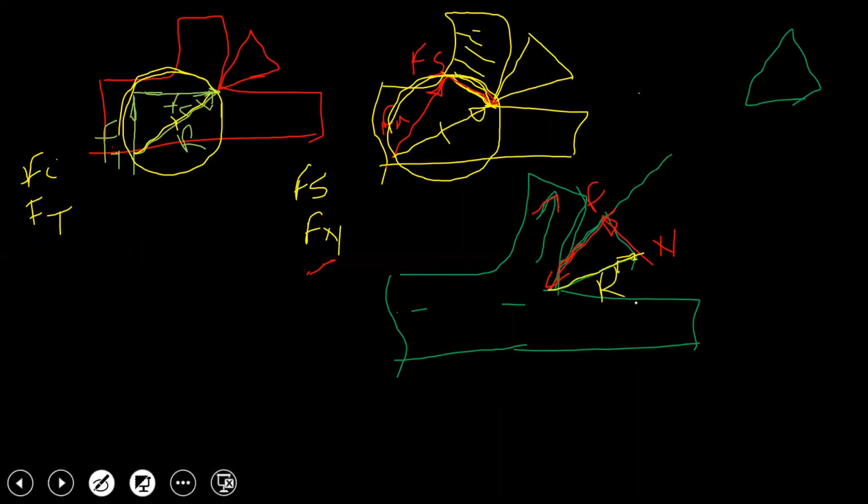So this is a resultant. Now instead of drawing it over here, I will draw this frictional force, so instead of putting it over here, I have shifted it downward. Direction is same, so I can relocate that force, right? That is the principle of transmissibility that you need to look into in engineering mechanics. So I have drawn frictional force over here.